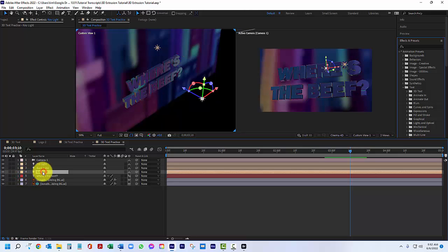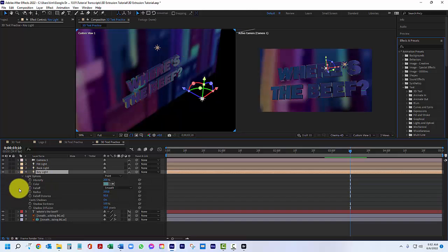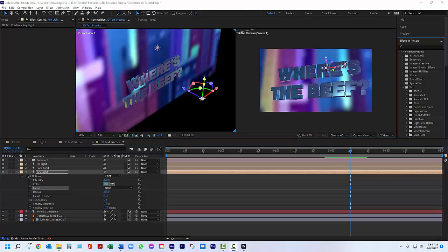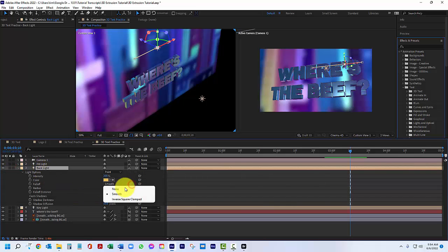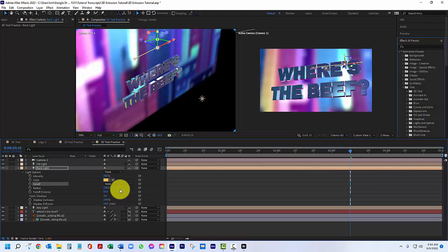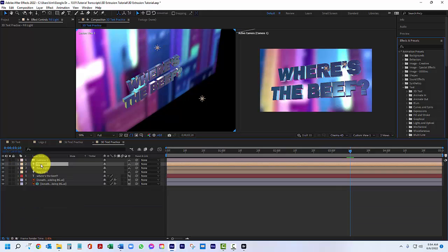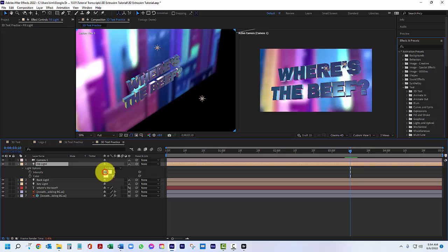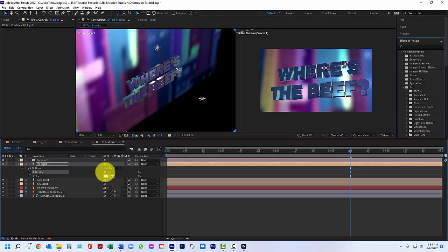I'm going to go back to the key light and I'm going to type AA. And I need to set the falloff to none. And that's going to dramatically brighten up the scene. There we go. That's more like it. And we're going to do the same thing to the backlight. Let's twirl that up. AA. Set the falloff to none. And now, wow, that's really too bright. So I'm going to go back to the fill light and bring the intensity back down. I think that's pretty good.